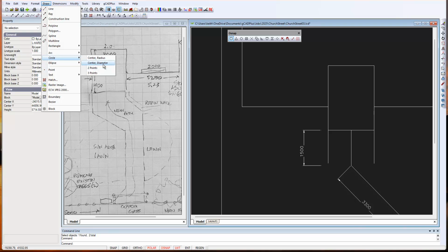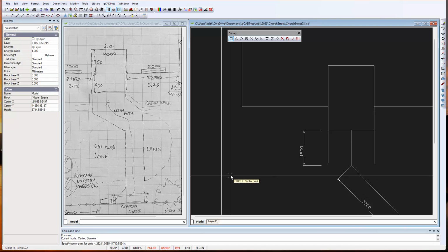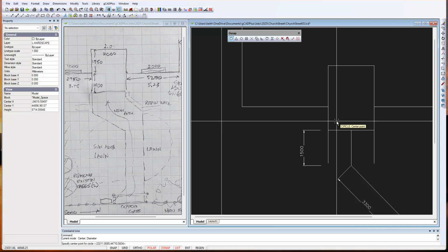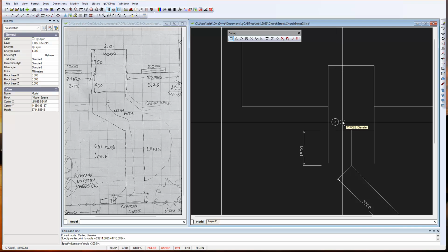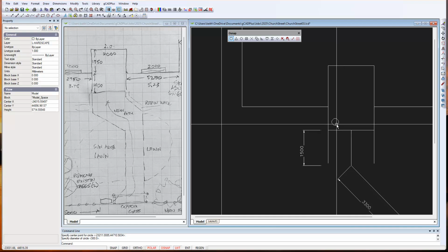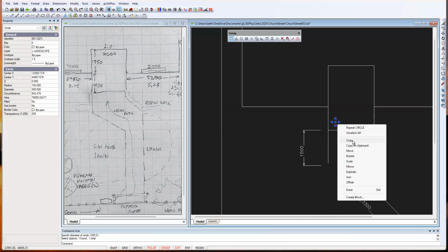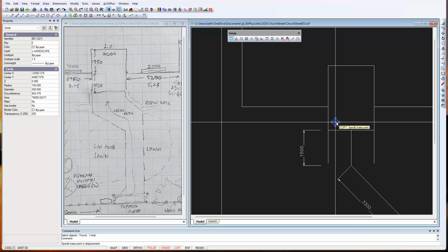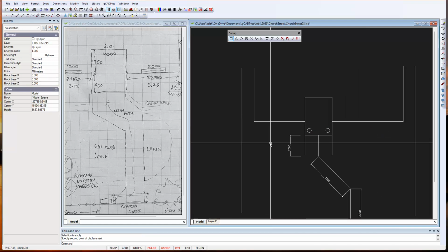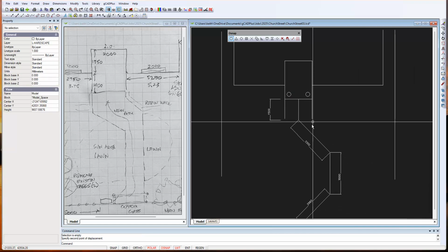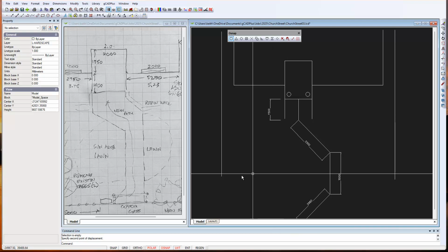So let's center. Now, we're not terribly interested in precision here, so we'll just say it'll sit there, and we pull out, and the prompt's asking us for the diameter of the circle. So I can just hit 300, and then we can copy this circle. You can do that by jumping to the midpoint and just moving across. So that represents our pot plants sitting on the veranda.